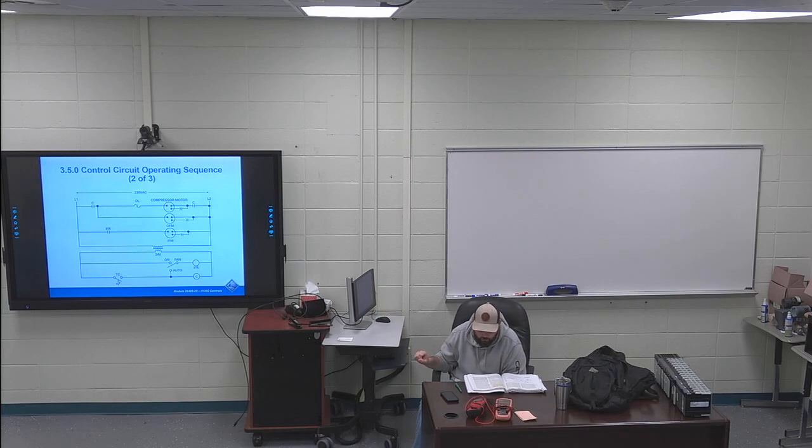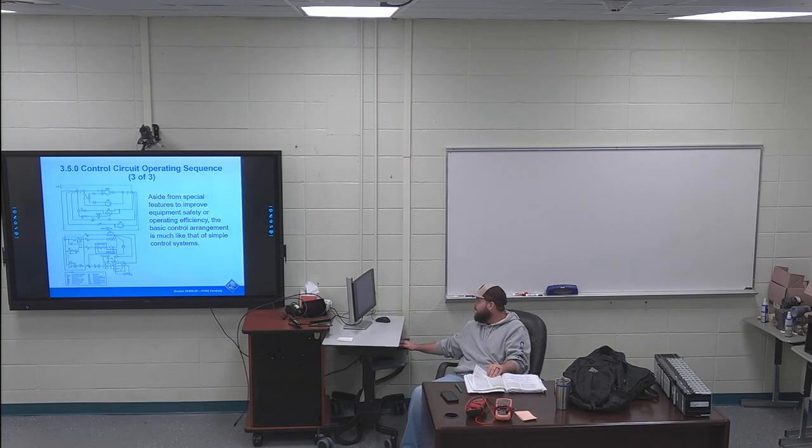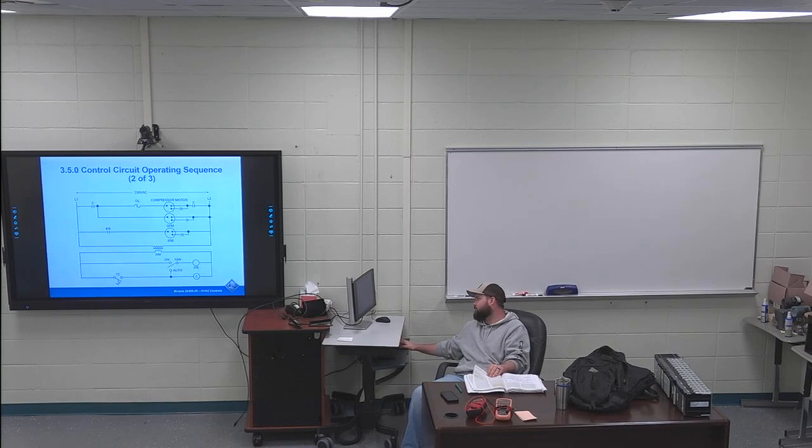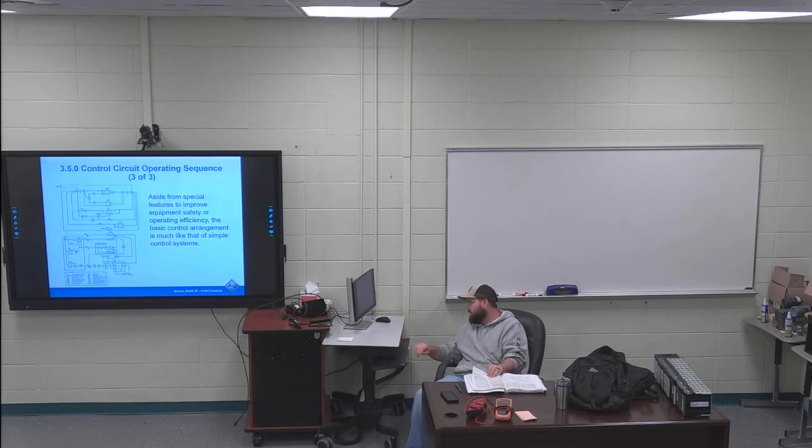The cooling component has more extras, such as a compressor short cycle protection circuit, a crankcase heater, and a current-sensitive overload device. Take away these components and you have a circuit that is identical to the one in Figure 36. So that's just comparing these two different ones. This is just cooling. This is adding a natural gas heating element to that.